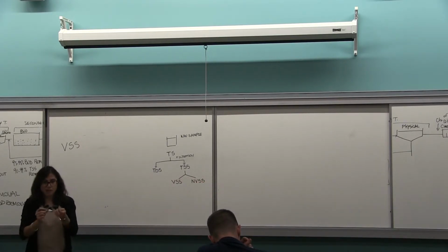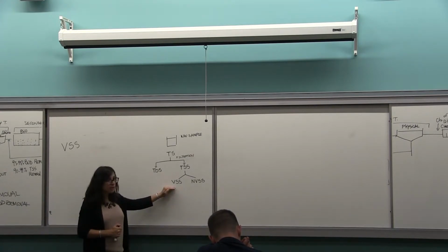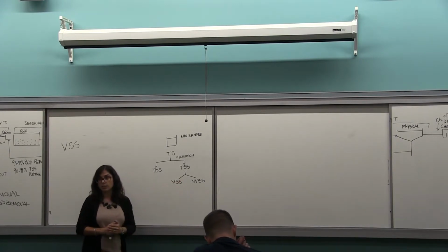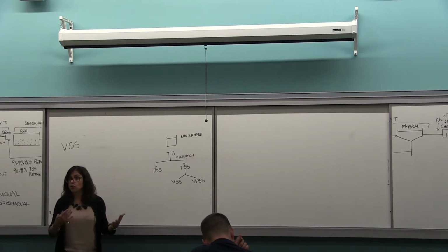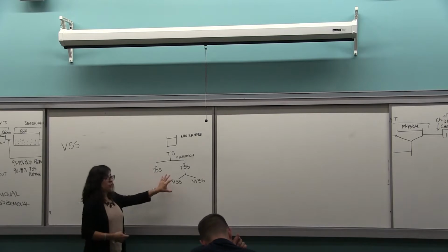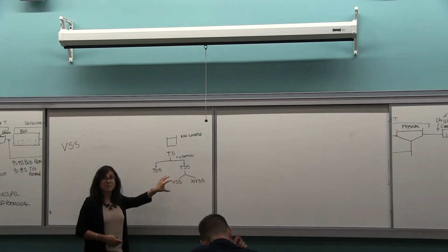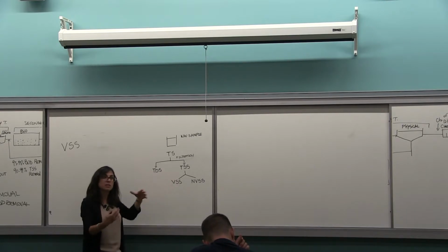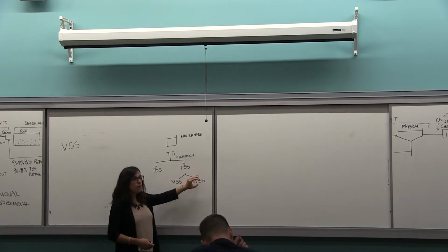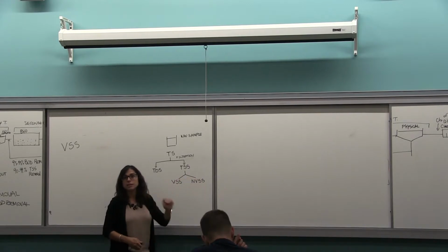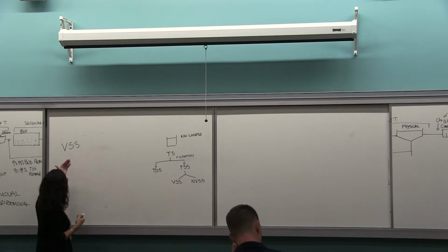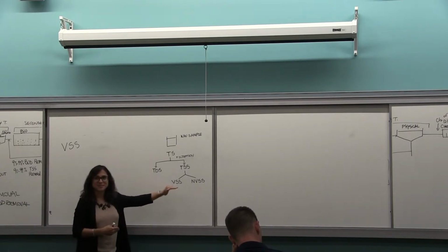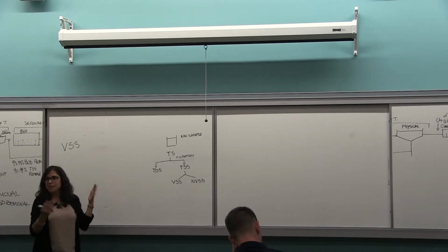The suspended solids, we can also divide them into volatile suspended solids and non-volatile suspended solids, depending on whether you can burn them or not, whether it's organic or inorganic in nature. So volatile suspended solids can be burned, and so usually are organic in nature. Non-volatile suspended solids are inorganic and cannot be burned. So the problem was asking us to find the volatile suspended solids and gave us a lot of information.